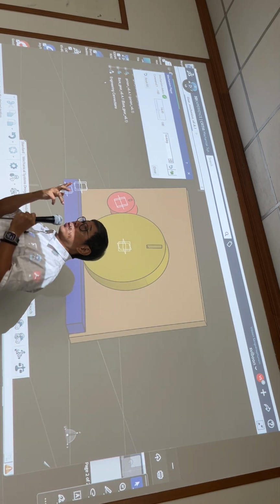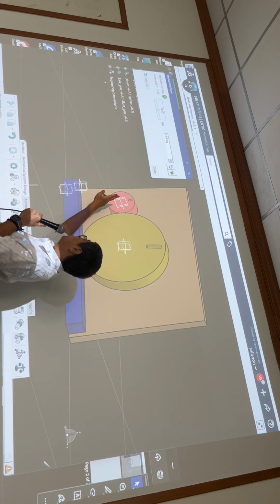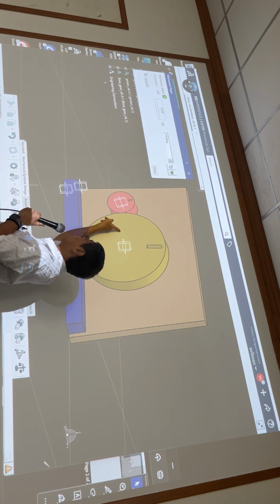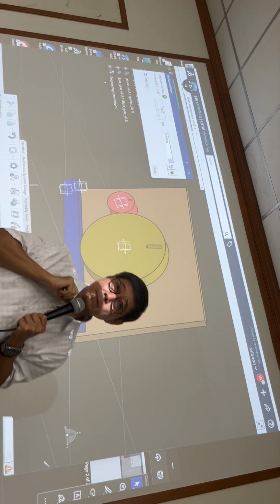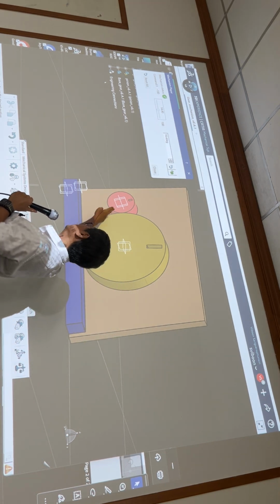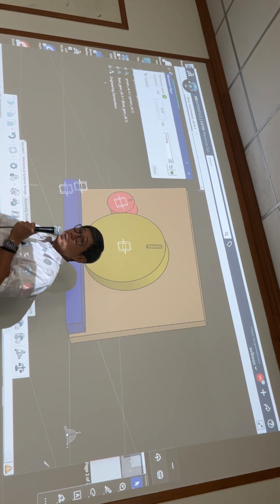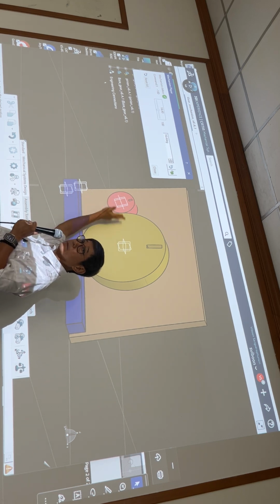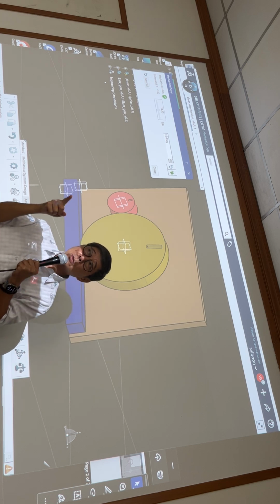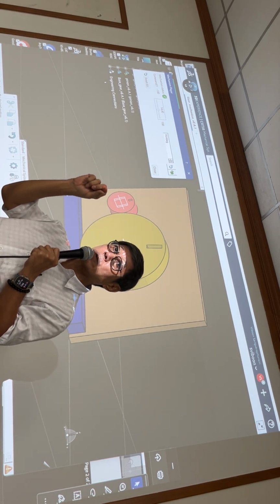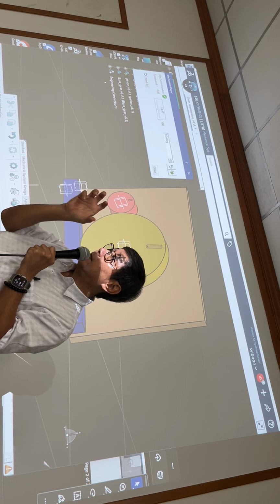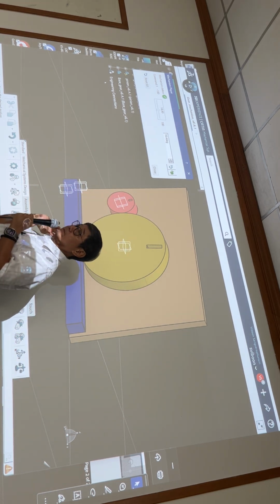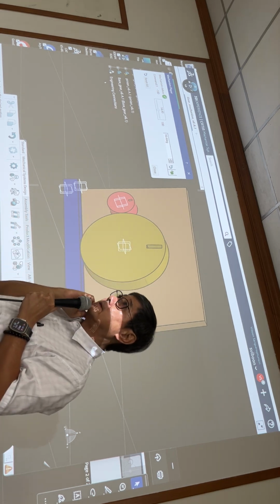You want to input, it's like a screw joint. If you input this one, and you want this one to move along with this one, this and this one have to be a gear joint. So a gear joint connects two revolute joints. Right? The screw joint compound is composed of an offset and a rotation, right, but this gear joint is between revolute joint and revolute joint. Right.